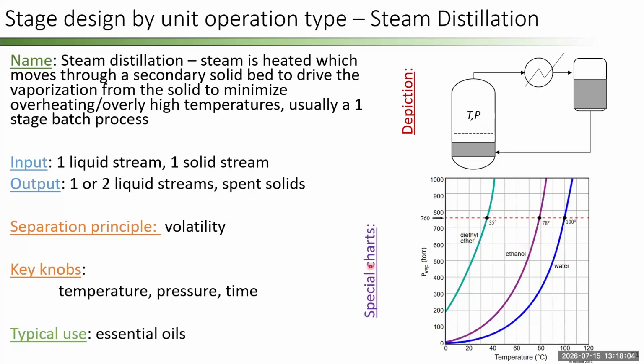right? So if I look down here at the temperature versus vapor pressure, I can change, by changing the pressure in the system, the temperature at which the water will boil, right? If I lower the pressure, just like going up in the mountains, say I lower the pressure in that vessel down to 600 torr, I can have that system run at 95 C rather than 100 C, right?